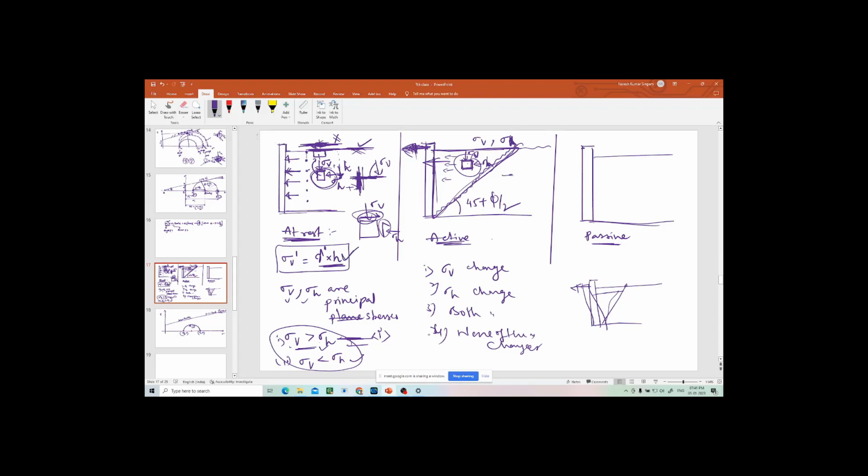You don't think that there is much height difference. There may be a difference between this layer and the next position, but the point was here and now the point is here. Actually it is very minor. You can't see with the eyes how much the retaining wall rotates when it is failing. It is like 1 degree, 2 degrees, and it will fail.